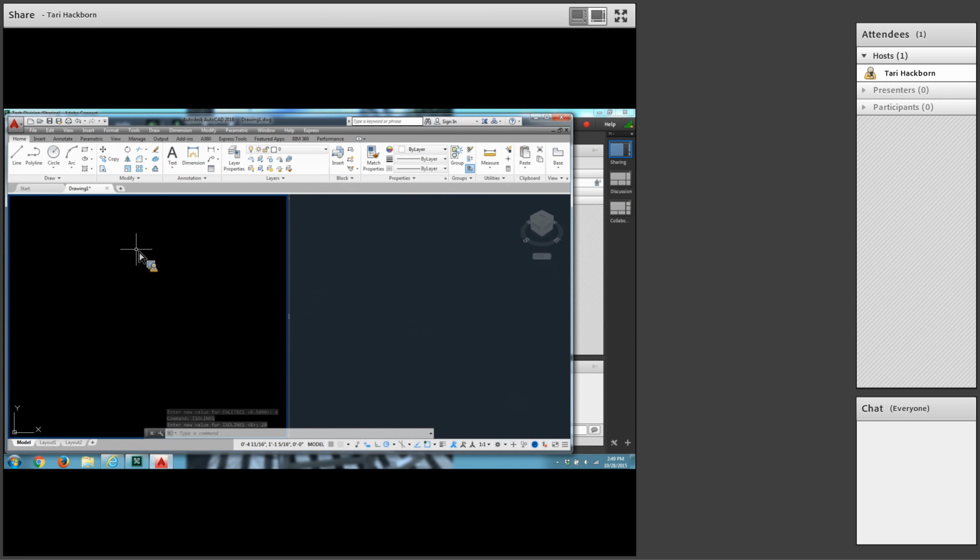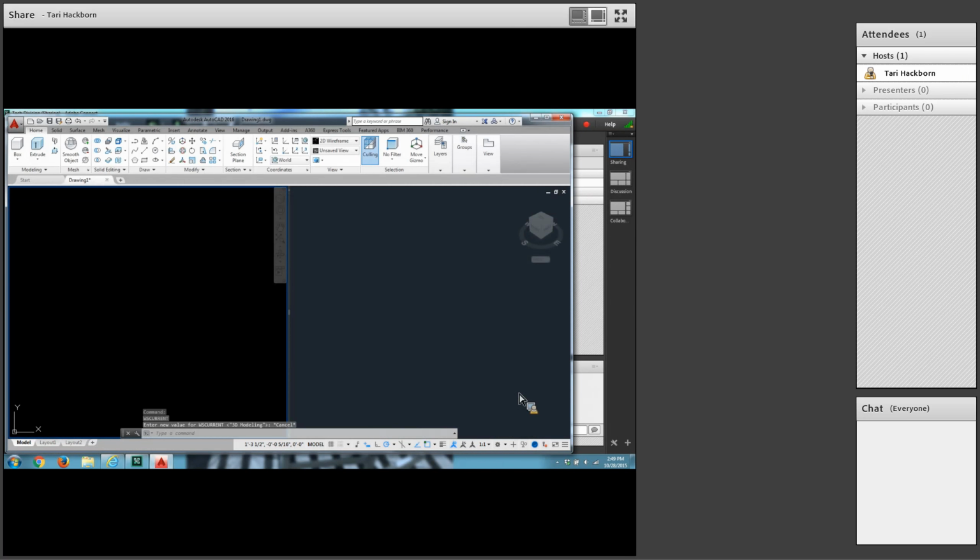Before we do, what we are drawing or modeling are 3D solids. So we will need to select this little gear down here at the bottom, or the arrow next to it. So these are down here on the status bar. You want to bring up the 3D modeling ribbon so you'll have the tools you need available. Okay, so I have a completely different ribbon up here now. Go to the 3D modeling workspace and you'll have 3D tools up here.